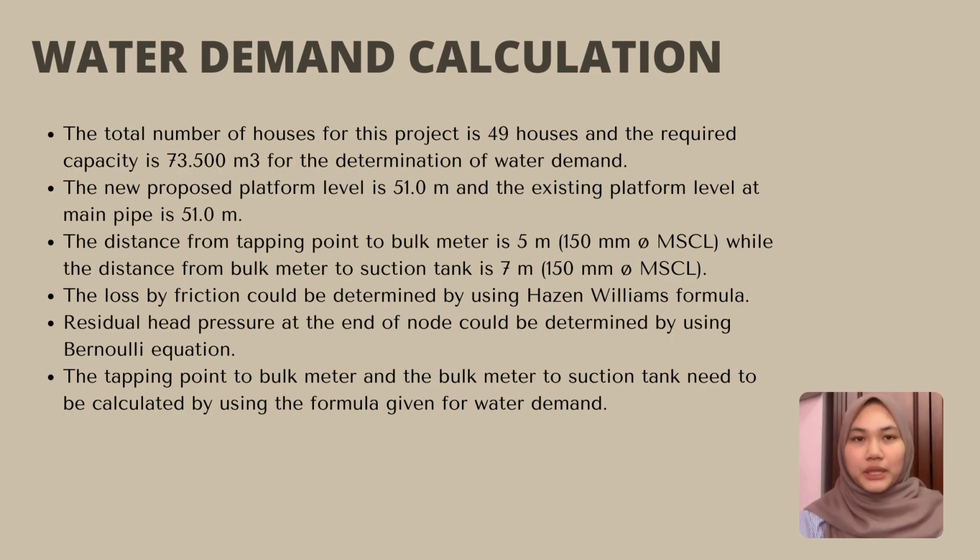The distance from tapping point to bulk meter is 5 meter, while the distance from bulk meter to suction tank is 7 meter, which is based on the reticulation system diagram. The design only considers losses by friction; the others can be neglected because they are too small.